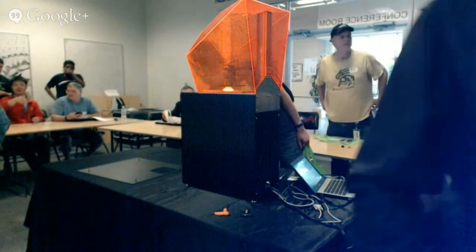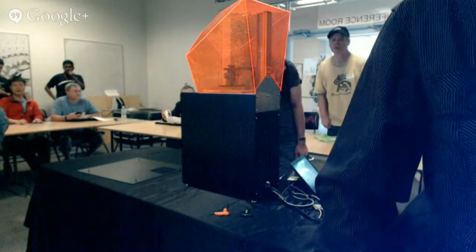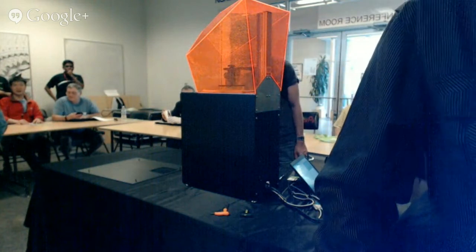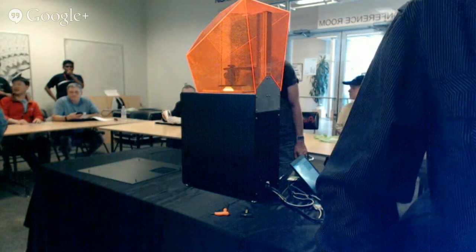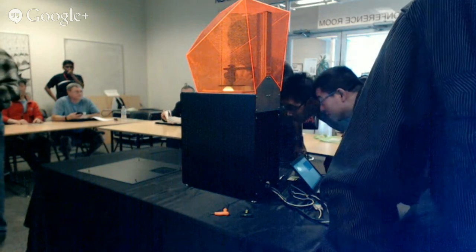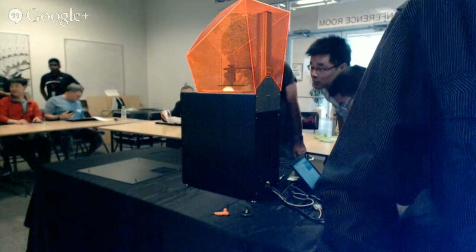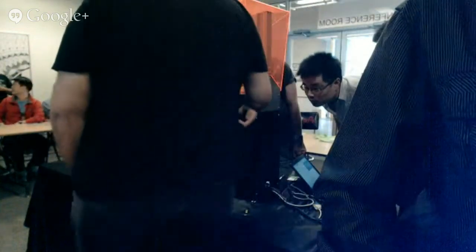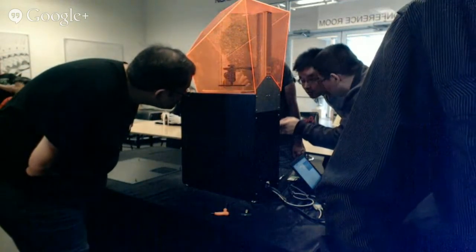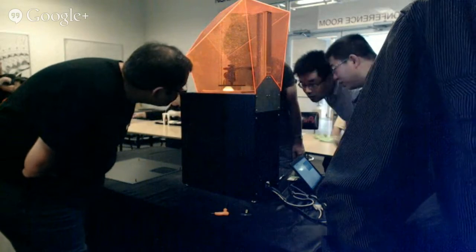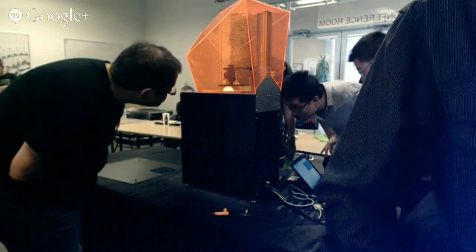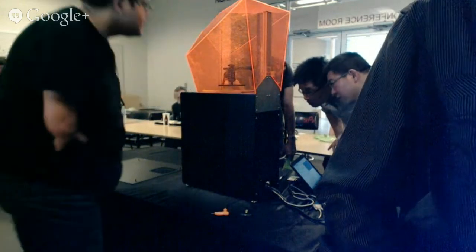Right. I mentioned before there's 4 chemicals that go into resin, right? And in particular, there's the initiator and the inhibitor. The inhibitor stops the resin from curing, and the inhibitor is fed by air. So the initiator is fed by UV, and the inhibitor is fed by air. There's tons and tons of air available. It supercharges the inhibitor. You need more UV to cure it. There's less air and more UV, then you get harder. Having this layer of air that sticks to the surface of the silicone supercharges the bottom layer of inhibitors in the resin. And that means that it stays liquid, doesn't solidify. And that makes silicone very easy to release from.